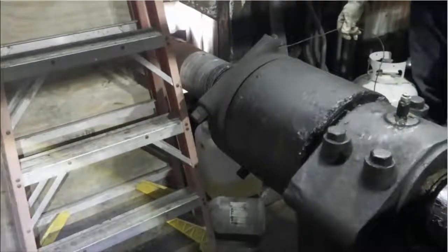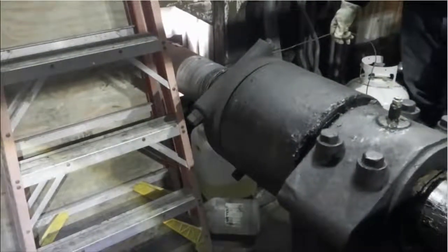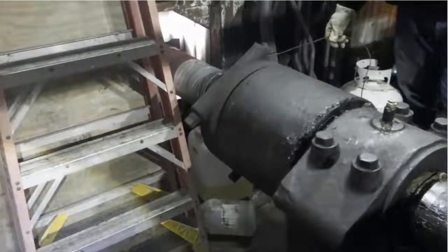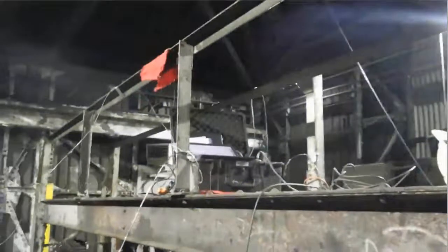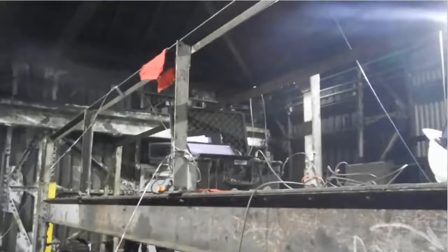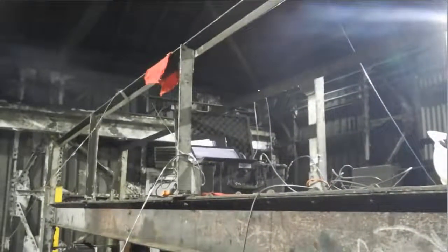At the top middle of your screen, you see the instrumented shaft. The strain gauges are protected and wrapped in duct tape. Operation is beginning as we pan over. The Hall effect sensor is positioned to indicate shaft rotations that we use to correlate strain data to lift height, and centrally located to the machinery is our data acquisition unit that records the strain and span position during operation.